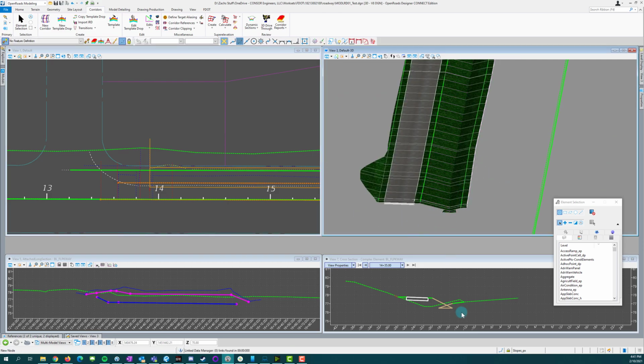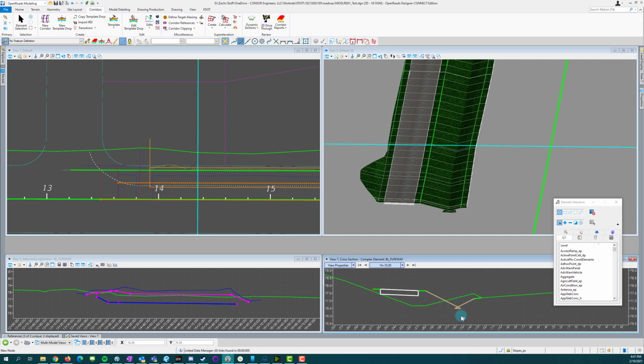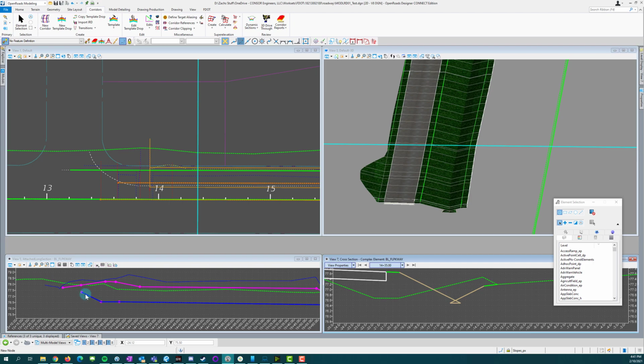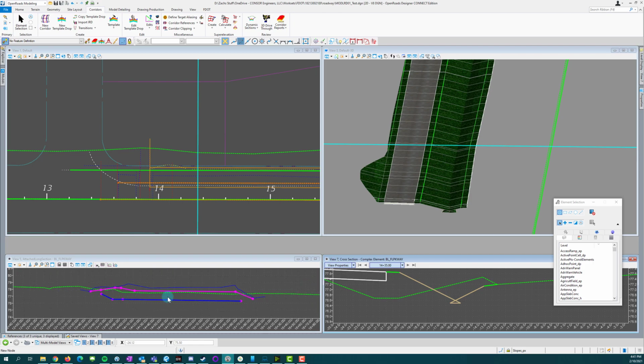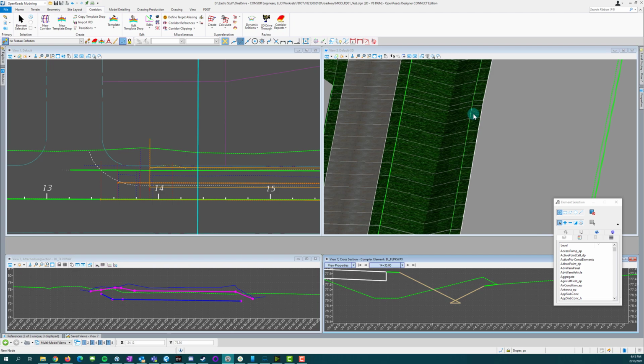So it may be that in this situation we're getting real close here to getting down to the bottom of the ditch. The weird part here was that invert that we had over here. So it may be that we need to sump this down a little bit. So maybe this ditch needs to come up a little bit. We come out, have a little sump, and then this comes up and flows back down this way. But it doesn't look like it's getting any better here.